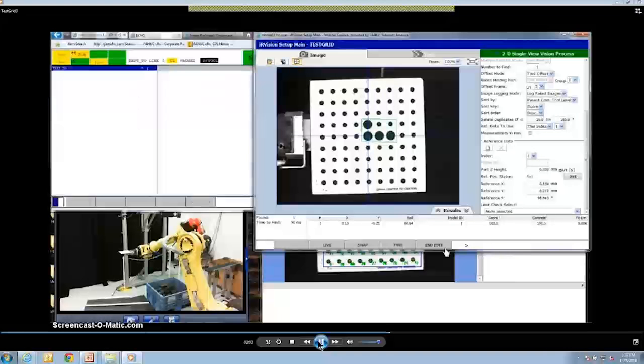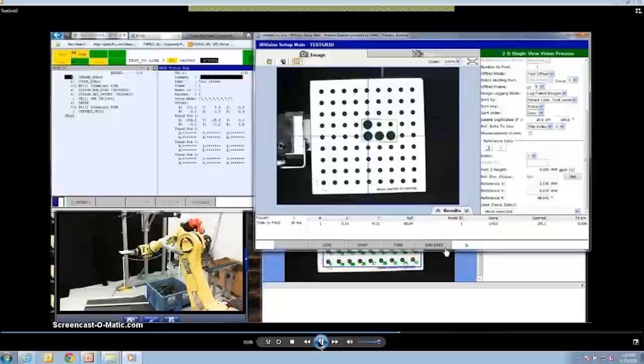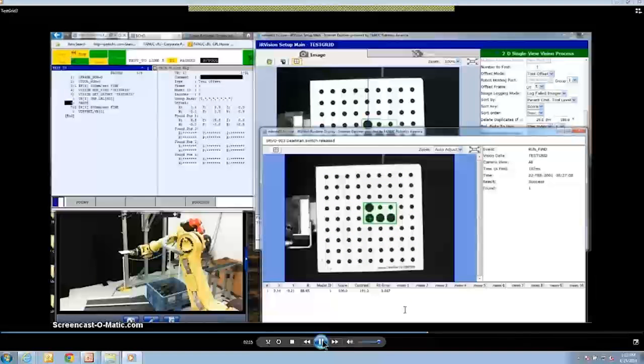So now that we haven't changed anything, we run our vision and see what our offset is, which should be 0, because this is our reference position. Here's our runtime screen, and here's our vision register. We can see that the offset is 0. The found position is what it was, 0.1, 0.2, and the angle was 86, that was just the absolute angle of the pattern. But our offset is 0, which you would expect because it's at the reference position.